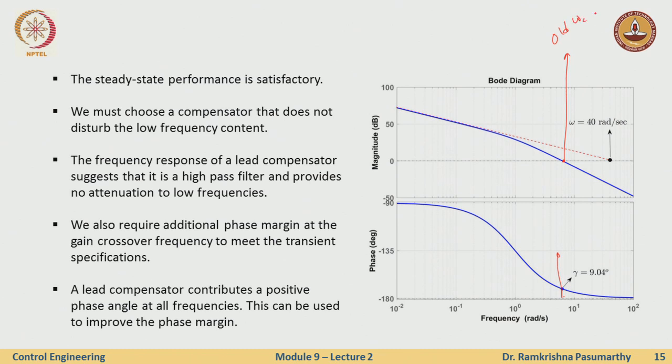This does not help me, right. Now, what should be the condition at the new gain crossover frequency, call it omega c. Okay. At this, the new frequency should be such that, with K prime, G of j omega Gc of j omega, the 20 log of this should be 0, okay, which means that now I know what this is at the new crossover frequency, right. I can just compute it by 20 log 1 over square root of alpha.